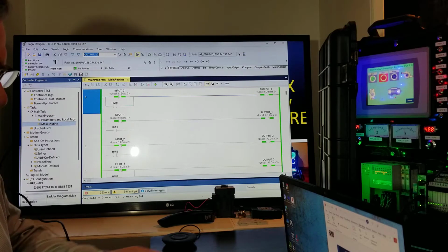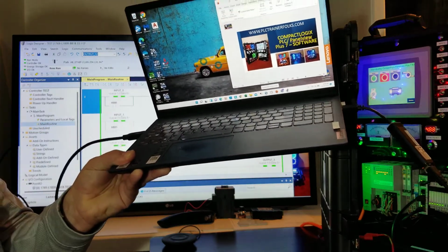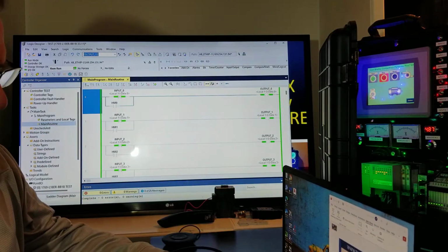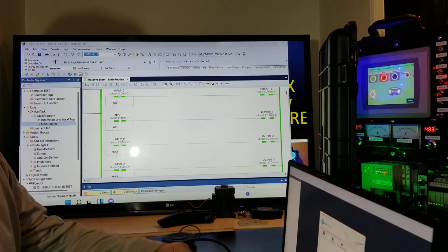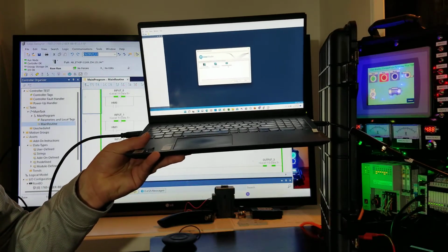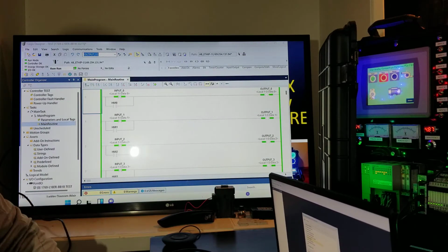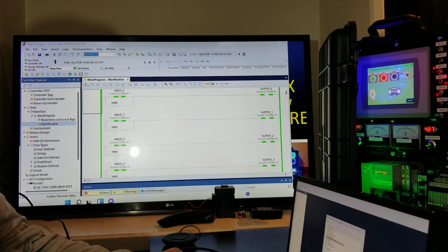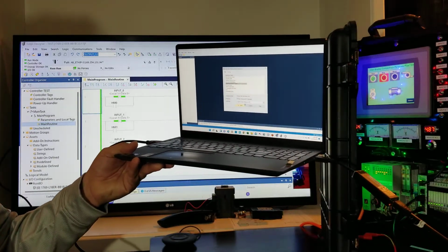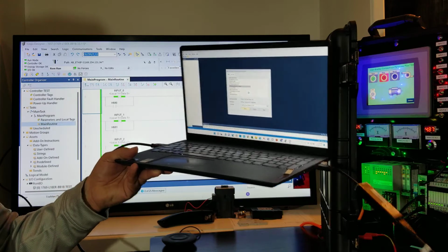It's called FactoryTalk Studio. You can see it. I put it on the taskbar there. So let's open the FactoryTalk View Studio, and I've clicked it. It opens a lot faster. We're going to use the View Machine Edition for simplicity for our PanelView Plus 7, and we'll use the PanelView Plus PLC trainer. So we've clicked it and we are opening it.